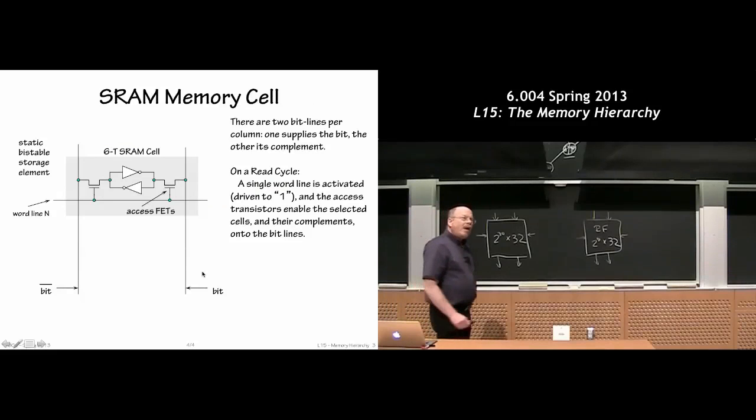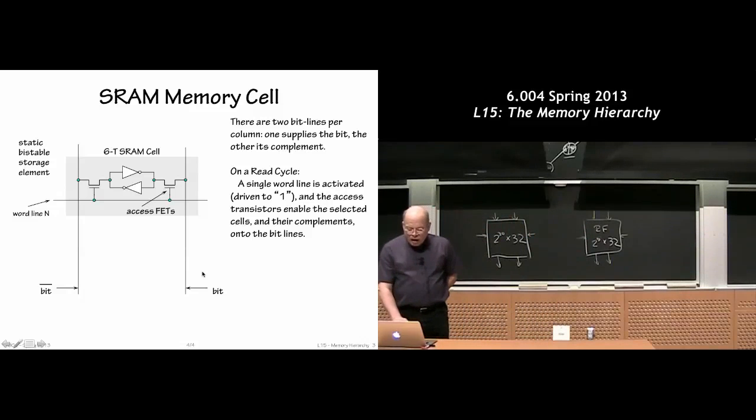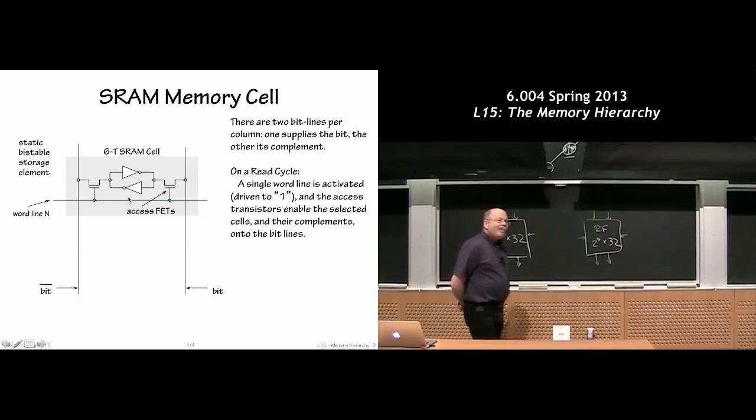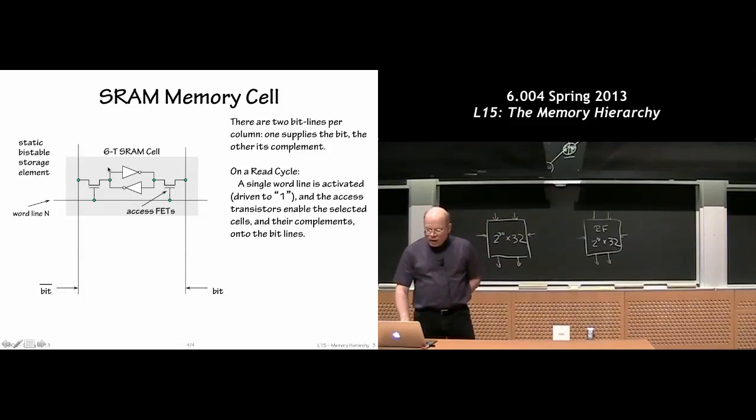Okay, so first up on the list is the sort of technology that we're using inside of our register file, a so-called static RAM. And at the heart of the static RAM, I hope you recognize that diagram. It's a little bistable loop made by a little loop of inverters. And that loop will reliably remember a value. So if I have a 0 on one side, I'll have a 1 on the other side of this little loop, the other side being the other of the 2 nodes. And as long as I keep it plugged in, even if there's a little bit of noise and one of these voltages gets slightly corrupted, it'll be restored by the logic gates.